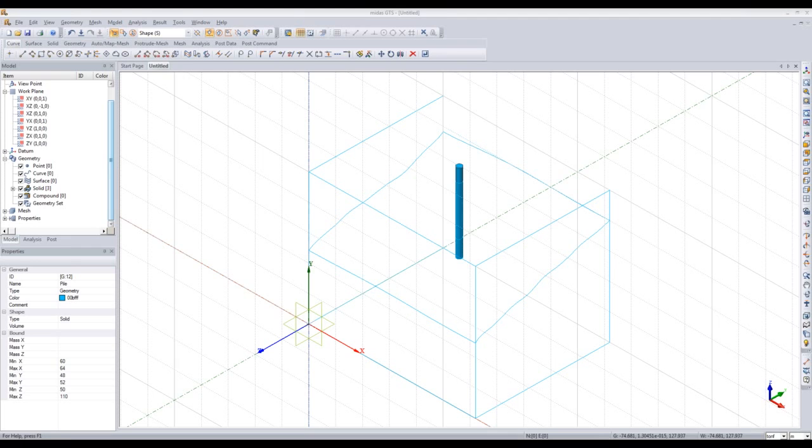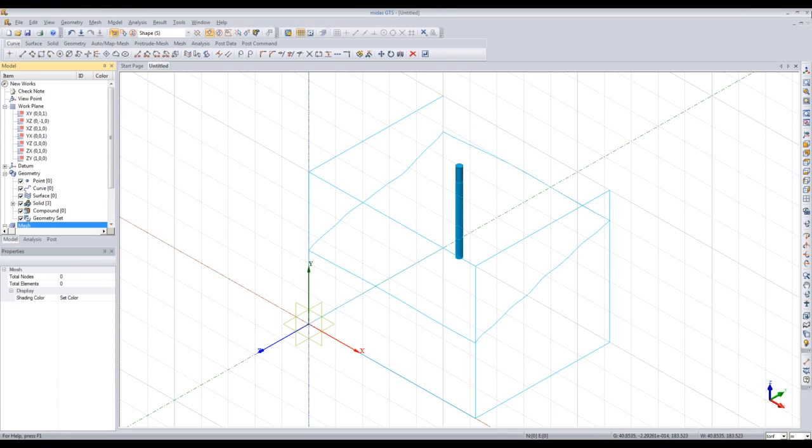Okay, so I'm reading the question tab now. Amr says, do you have to use the Boolean cut or can you use embed? That's a very good question. So let me just refer to the left over here. Just give me a second. I just want to set this up here. As I said, the cut is the better option, but if we embed the pile solid into the ground, the upper part above the ground will be deleted.